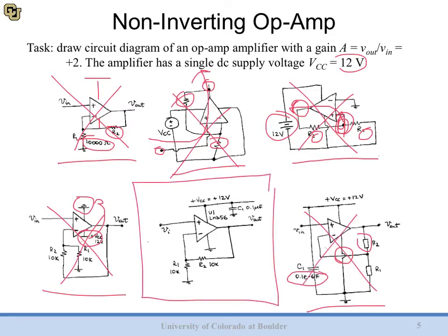The schematic that we really like is this middle one on the bottom. You can see we've labeled all of our components with designators or names. All of our components have values. We've labeled input and we've labeled output. You can see we used microfarads instead of 10 to the minus 6. Voltage rails are above ground rails. Data flow goes left to right. It looks really good. We like this one. Aim for something that looks like that when you're drawing circuits.